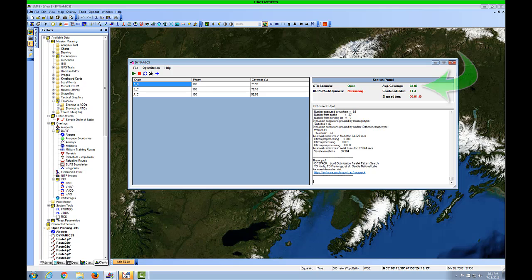You can see that overall the average coverage has improved from the original 19% to over 68%, with excellent coverage provided to all 3 of the voice bridge groups. Remember that for our naively selected orbit, the second 2 groups had no coverage at all. The deviation in coverage has also decreased substantially. Better and smoother coverage is the result of this Dynamics-generated orbit.